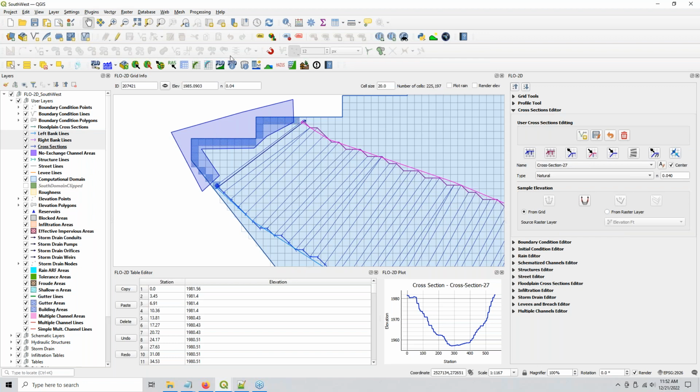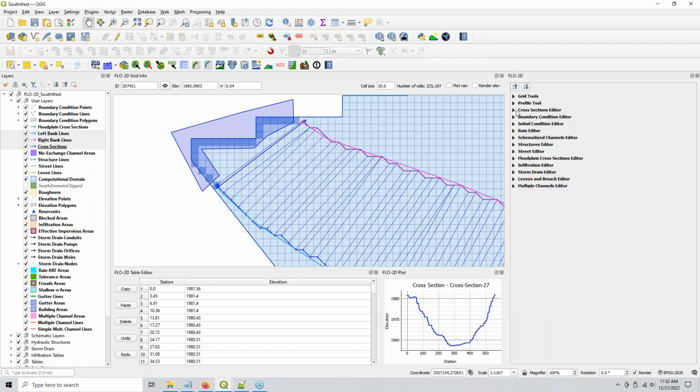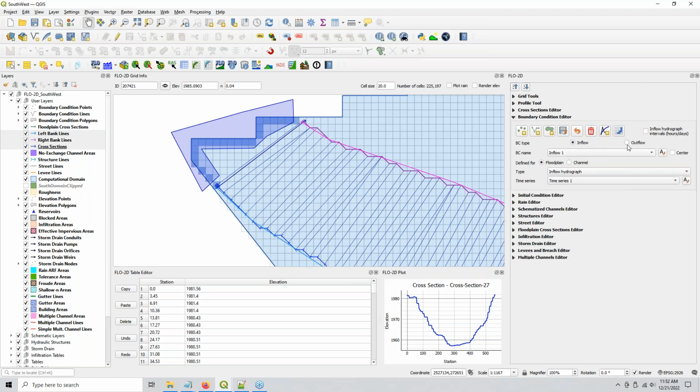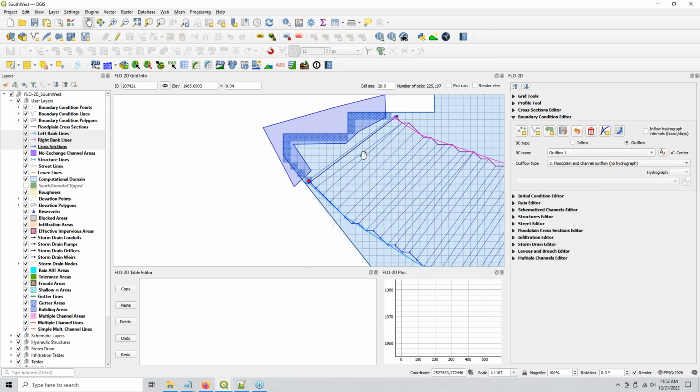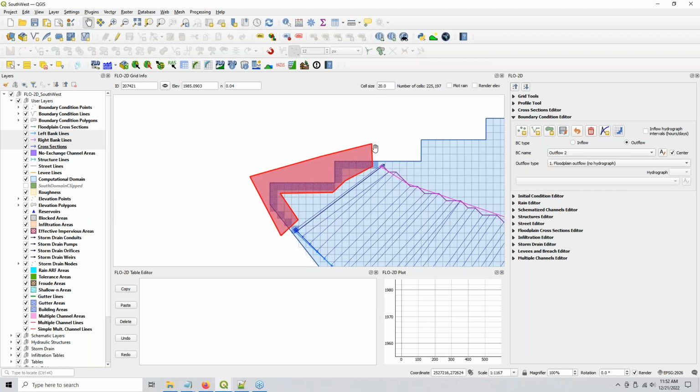And as you can see in this case, let's see if the boundary condition is in here. I took this guy. Let's do this. That is your channel, and then this guy here is just a polygon along this boundary, and then the Flow-2D plugin will identify which of the nodes become the boundary. So you don't have to go in with a polyline or dots or anything and try to set these up individually. You can set them up with a polygon.